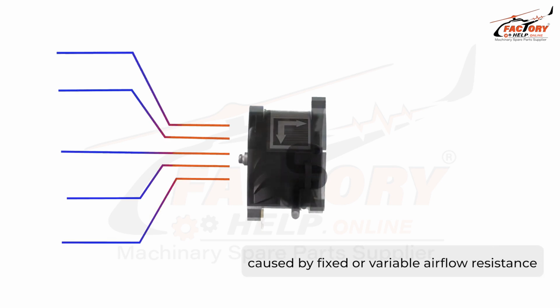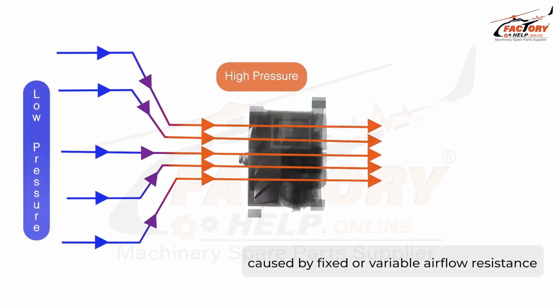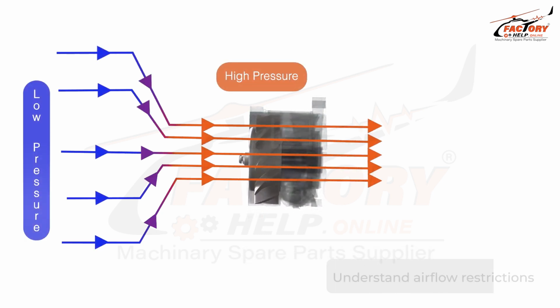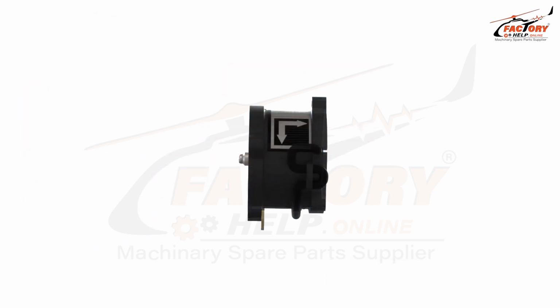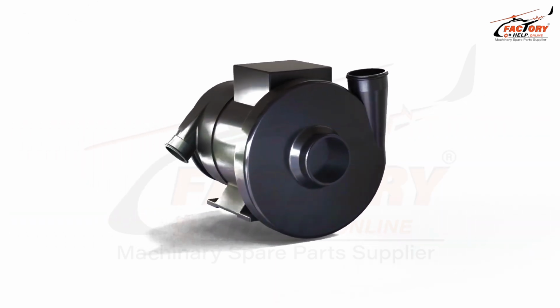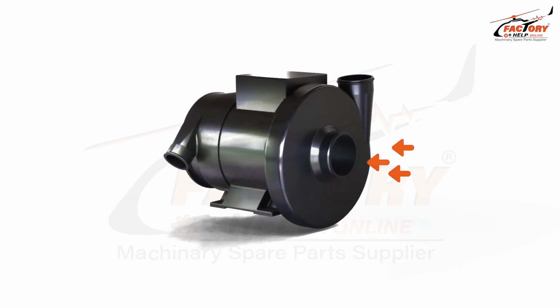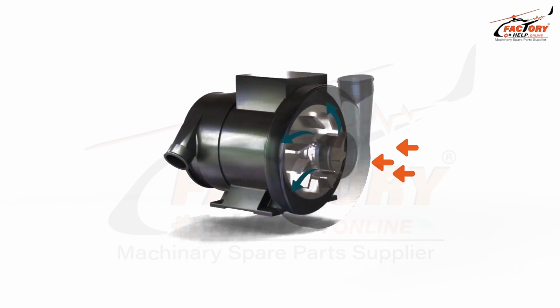Using an airfoil section is the most efficient way to generate airflow, giving the most flow output for the minimum power input. This makes an axial fan the perfect choice to produce high airflow in a compact, lightweight package. However, like an airplane wing, a fan blade will stall and stop generating flow when it encounters certain conditions.